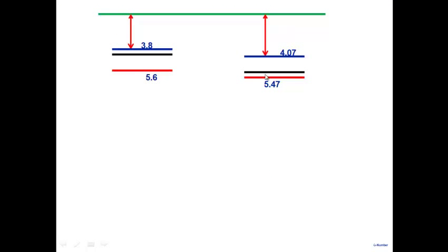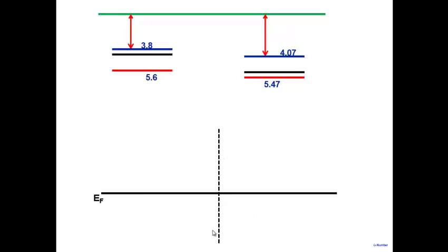So let's have equilibrium then. The starting point is EF, constant throughout. You draw that. Then the next point is draw the interface here. Far away from the interface, things are the same as before. So we do this here. We locate where far away this semiconductor is. So EC is close to EF here and EV is here.